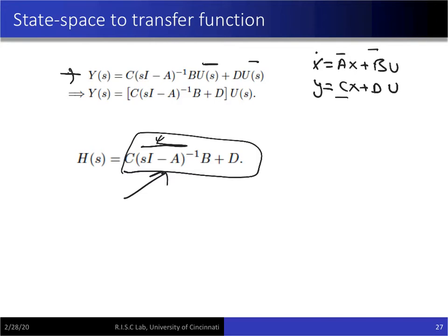Again, how many transfer functions are there? Again the same, m into k. Your Y can be multiple outputs, and U can be multiple inputs, so it will be a matrix of transfer functions. For each input-output pair, you will get one transfer function. Okay? Questions here?